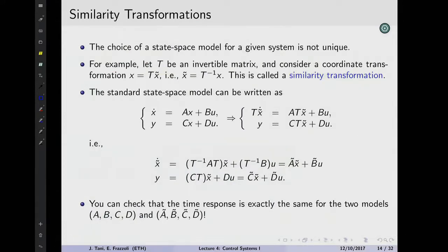So this was our little excursus on discrete time systems. It's the end of the side step I was talking about before. Now we got to the point where we can tell how to express, both implicitly and explicitly, a continuous time and a discrete time system, and how to do a basic analysis of the stability. In both cases, it depends on some structural properties, on the eigenvalues of the A matrix, whatever A is in the specific case. Now let's go back a second to continuous time signals and move on.